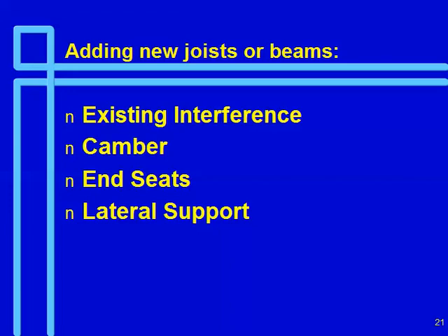And then don't forget that this joist that you're putting in needs lateral support. When you design a joist or specify a joist on a plan, the joist is designed with the assumption there is a lateral support every 36 inches along the length of the top chord.